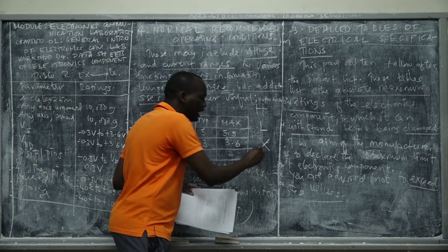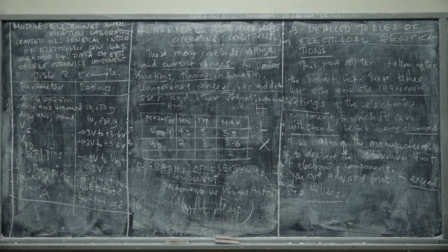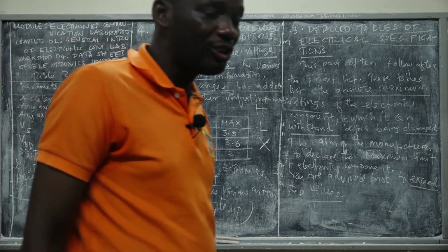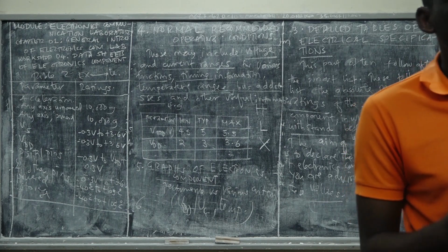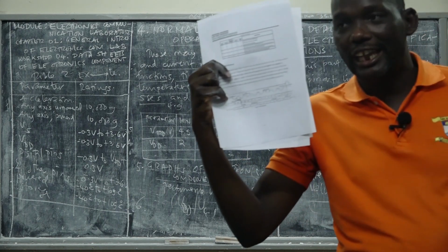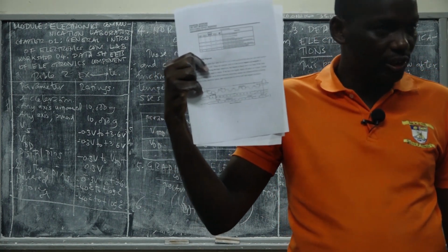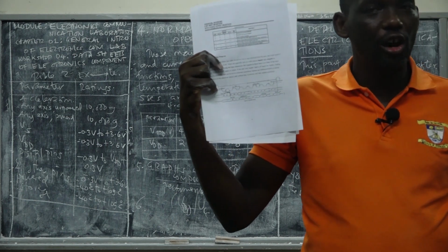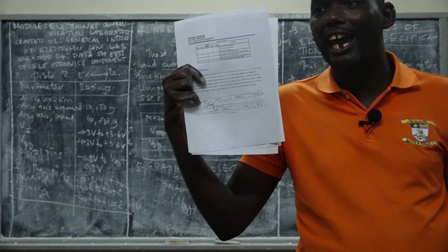So in the truth tables mostly shown by these data sheets, we don't use 1 and 0. You are experts at drawing truth tables using 0 and 1 bits. But the truth tables in these data sheets use three notations to represent the bits: H for high, L for low, and X for the digital component doesn't care.